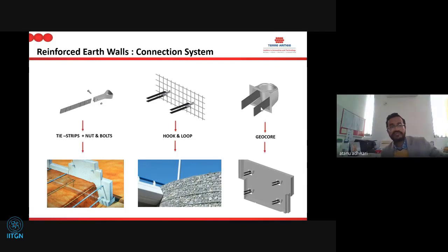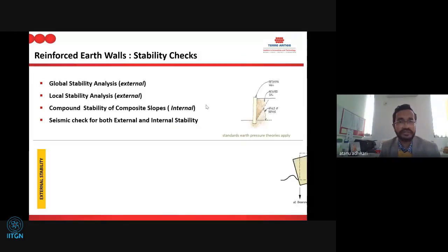If you have steel going through, even a minor crack matters, because we are talking about a 100-year life, not 10 or 20 years. Even a small crack will corrode the steel, even if it is still passing through the hole. So the idea is to develop a system where there is no steel component, and that's why all this concept has been developed. Sorry, I don't have many more slides, but I just want to show you one small video.